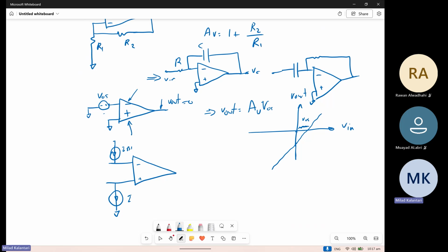So internally they may need some bias currents, right? Which we are not seeing from the outside, but they are there. So we figured out that this current drawn for the bias may cause an extra voltage change or extra offset somehow once you are trying to put in your feedback.